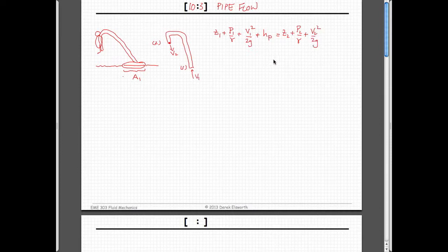And let's write out the other components, just continue on this line. So the major losses are going to be friction factor, length over diameter of the pipe, and velocity in the pipe squared over 2g. So I'll just write them out, then we'll talk about them. And the head losses are going to be a loss times v squared over 2g.